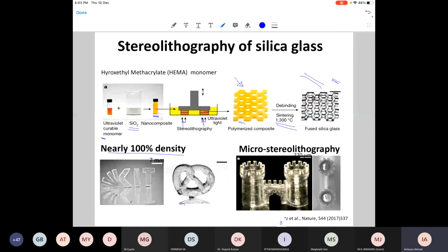If you take these two, you can get silicon nitrocarbide, and if you take only this one, you get silica. If you take only this one, silicon carbide, and so on. But generally people take a mixture of two polymers mixed, and you get a pre-ceramic polymer, which when you pyrolyze, you get a ceramic product, which is either silicon carbide or silicon oxycarbide.